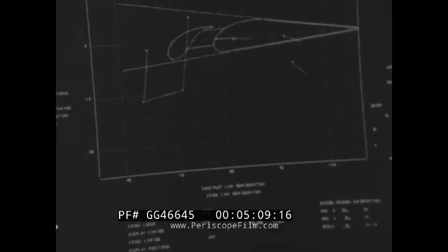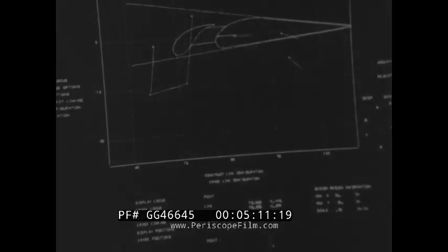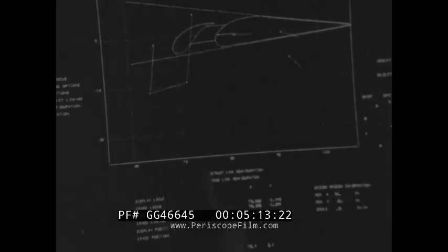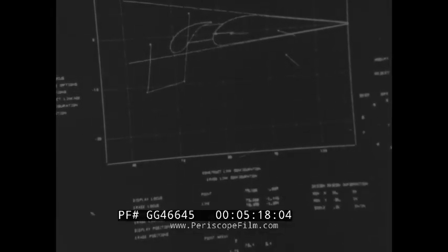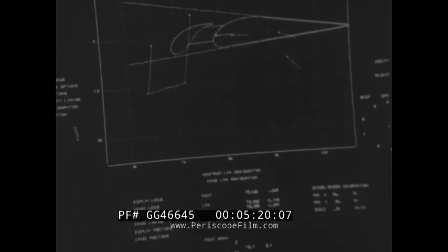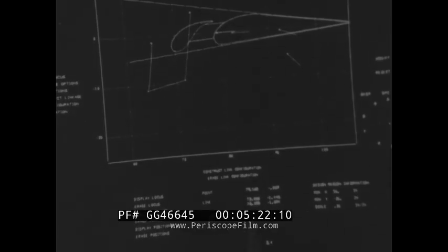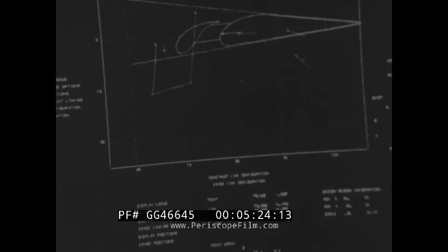To rotate or animate the linkage, the rotation option is used. The increment of rotation and the direction, clockwise or counterclockwise, must be specified for the link of the 4-bar linkage previously designated as the input link. Intuitively, it can be seen that the direction must be clockwise to obtain the desired flap motion.